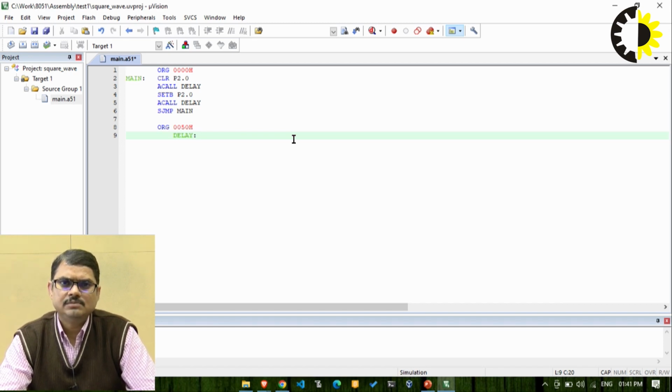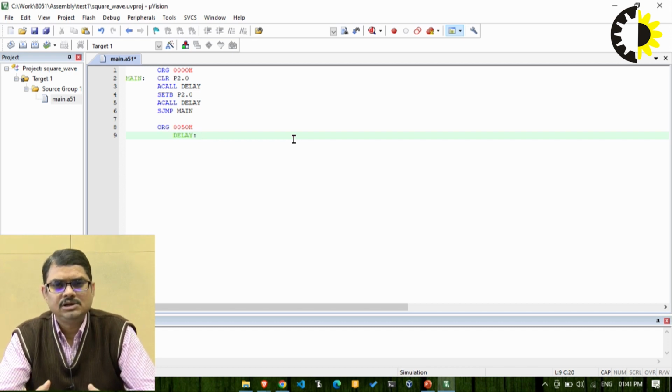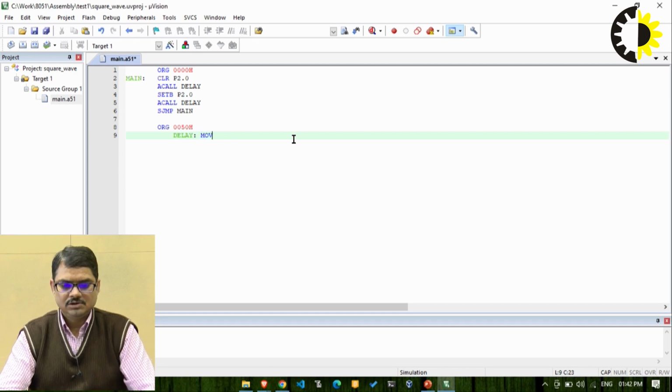In the delay, if we are not constrained with accurate or precise timing calculation, then we can put any value into any register, decrement that value and check whether it is 0 or not. So we are engaging our microcontroller in decrementing the register value and checking whether it is 0 or not, and thus we are basically wasting the machine cycles of the microcontroller, and these wasted machine cycles are termed as the delay produced with the microcontroller.